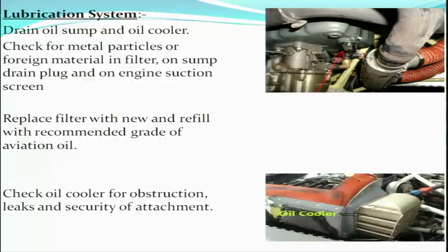Check for metal particles or foreign material in the filter. When we are replacing the oil, we also need to replace the oil filter. The old oil filter will be removed, a new one will be installed. The old oil filter is to be cut open and the paper element in the oil filter needs to be opened up and checked for any foreign material, for any metal particle on the filter.